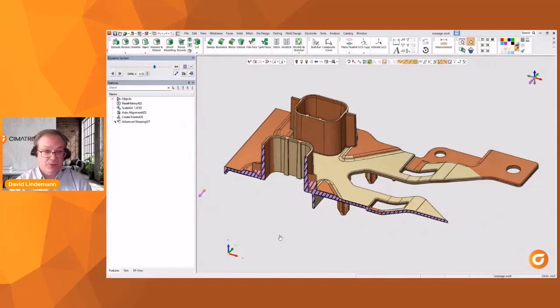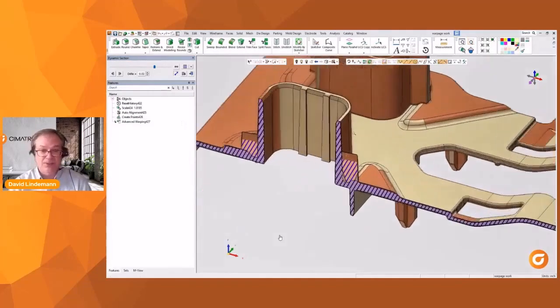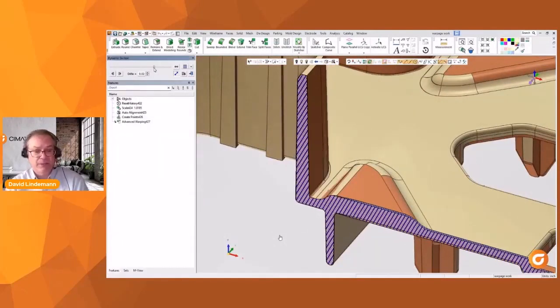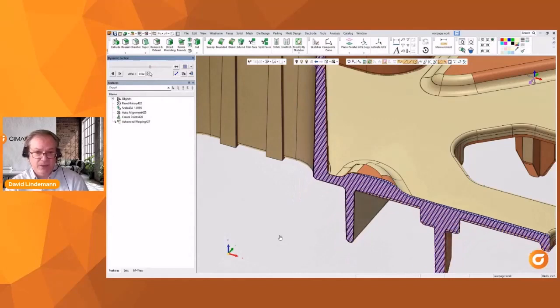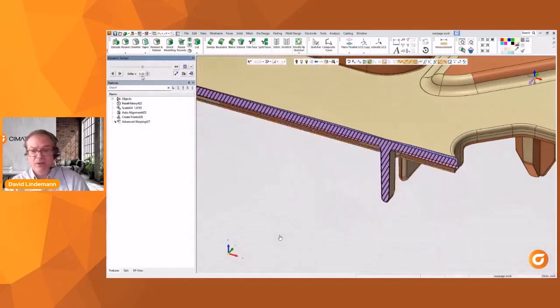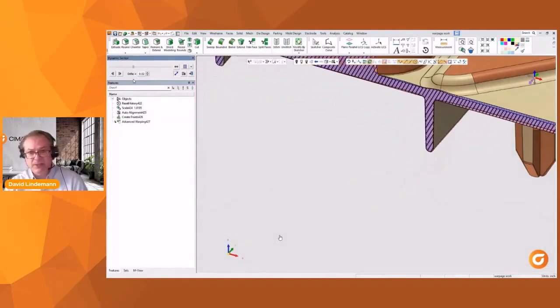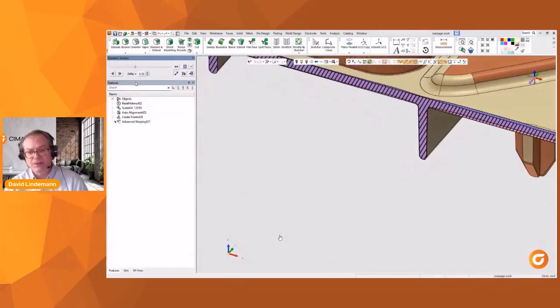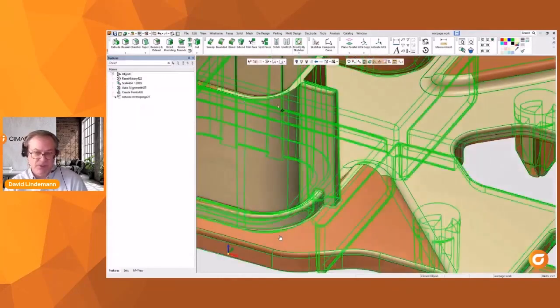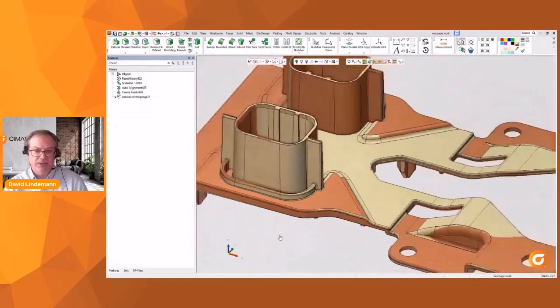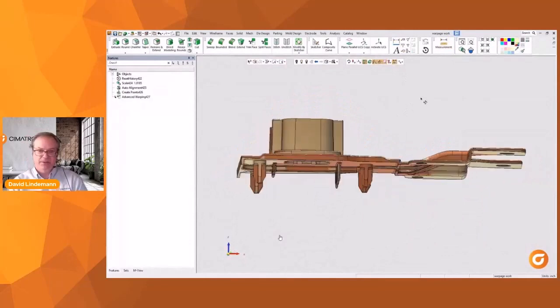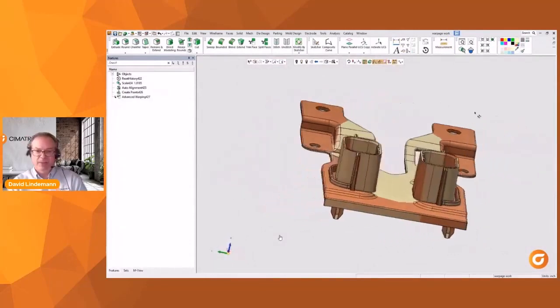Do I want to keep my rounds perfectly round? I would check for roundness. Exactly, especially if it's something like in a side pull. I would take a close look at maybe adjusting that to a standard round situation. Okay, well, how do I make these little tweaks? Here, dragging through, I'm still looking at the wall thicknesses, and you can see the near verticals, everything drafts out nicely. So the new draft I have is very comparable to the original draft, and I'd be very happy with that.